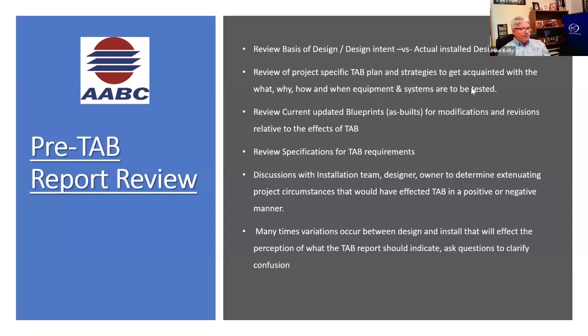Are things accessible? I know I've said that a couple times here. Accessibility is a huge thing in new construction. It's very easily overlooked in the testing and balancing field to say, oh, we put it all in that room, or we put it all above the ceiling. It's someone else's problem to get to it and test it. Well, if we can't get to it to test it, it's not going to get tested. Or it'll get tested in such a flagrant manner that it may not be exactly accurate. And now we're jeopardizing accuracy over accessibility.